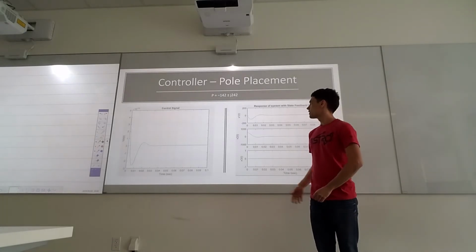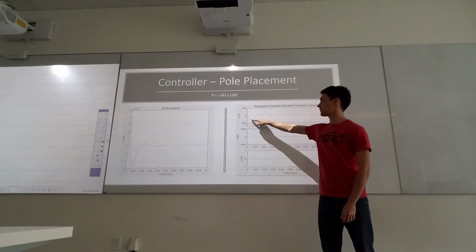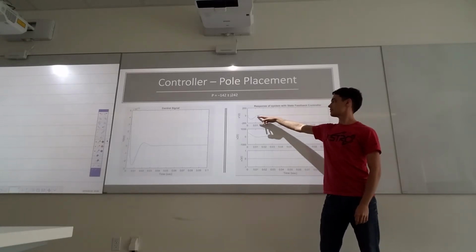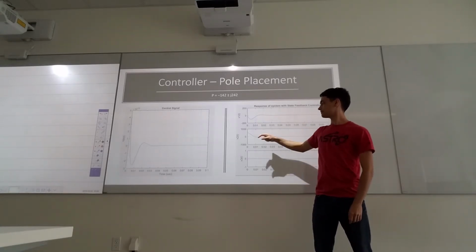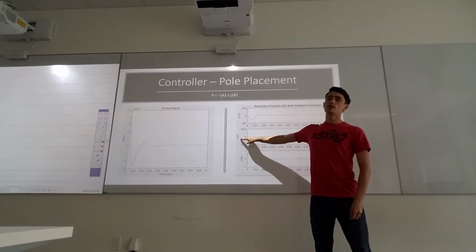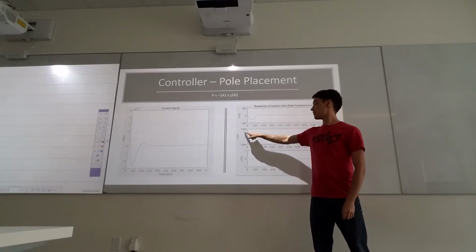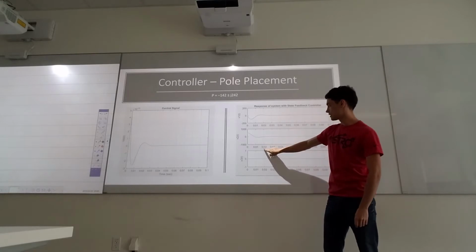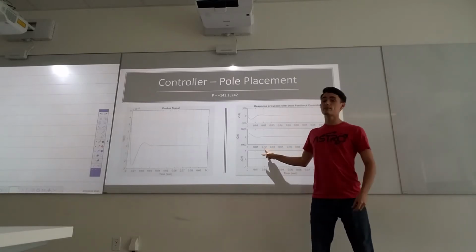So we can see naturally the system current goes down to about negative 100, and then has a little bit of an overshoot and steadies out. The radians per second of the motor also has some overshoot, and everything finishes responding and settles down around 20 milliseconds.